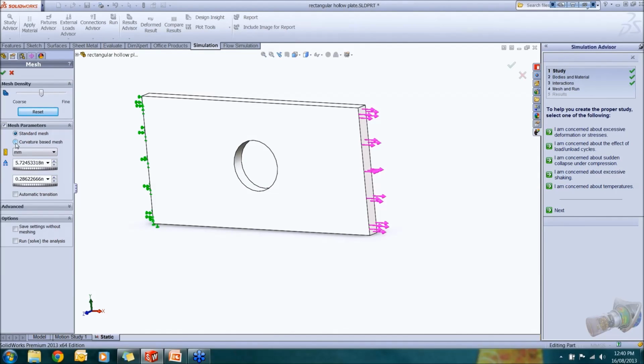However, we have a more advanced automatic mesh tool where we can specifically define the maximum element size, the minimum element size, and also the minimum number of elements in a circle and the element size growth ratio. Simply, maximum and minimum is what you assign, and the auto mesh tool, depending on the different features of the model, will adjust the element size to fit a high quality mesh everywhere.